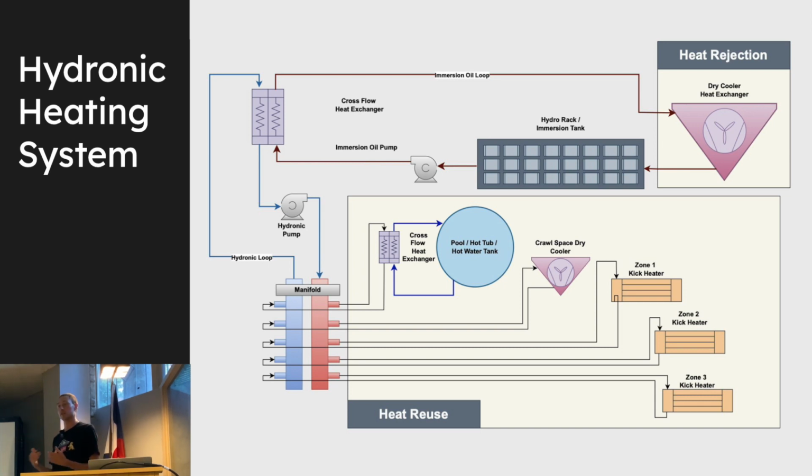It's about designing the system properly. There's a lot of pump sizing, radiator sizing, heat exchanger sizing. Make sure everything's optimally designed for your coldest day. Maybe it's overkill. Maybe the parts are 10 grand more to design it for your coldest day. So you say, screw it. We're not going to design it for the coldest day to save money. And maybe on that coldest day, you don't tear out your natural gas heating system and that picks up the slack. There's a variety of ways to do it. You can kind of split it up however you see fit. All these off-the-shelf components, they all exist, and then you piece it all together.